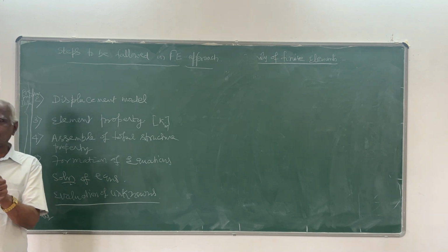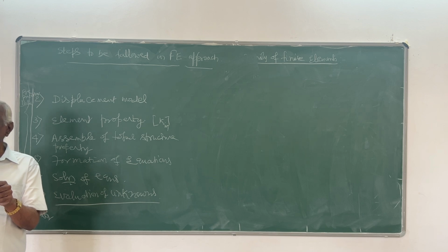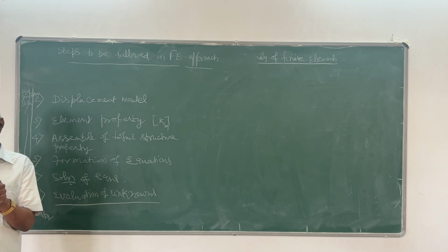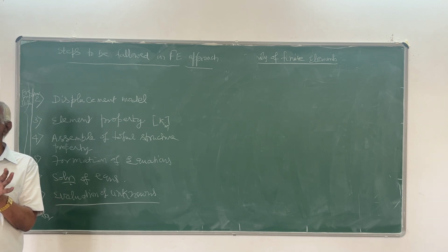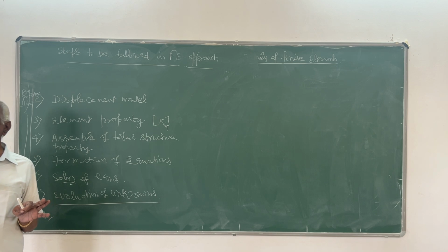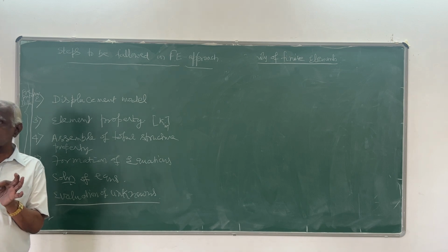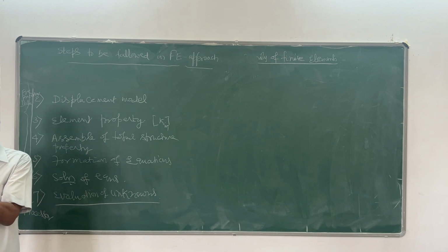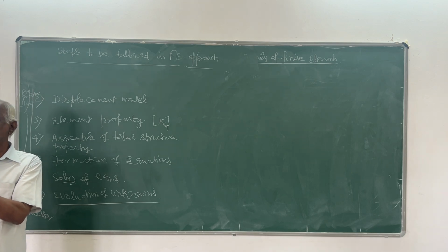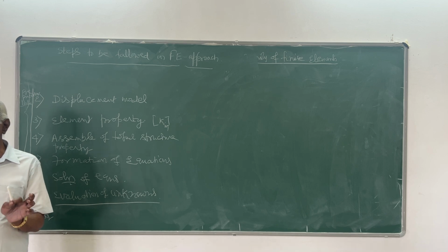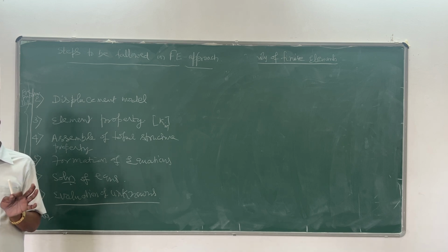In any direction at the ends, load or displacement can occur, but only linear, no angular displacement, because each joint is a pin joint. So that linear displacement, in the case of plane trusses, can be resolved along our two fundamental global directions, x and y, so we get two components of displacement.